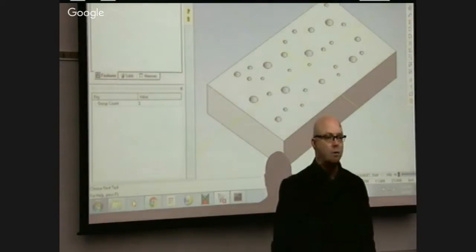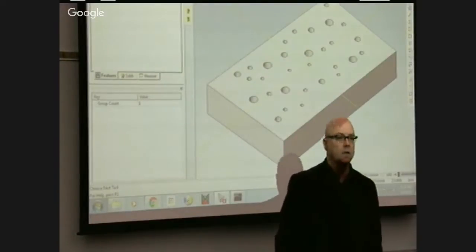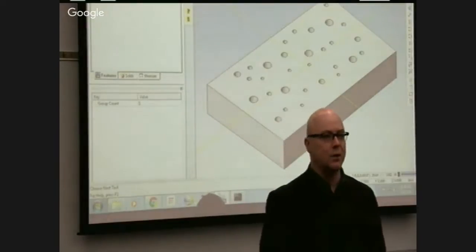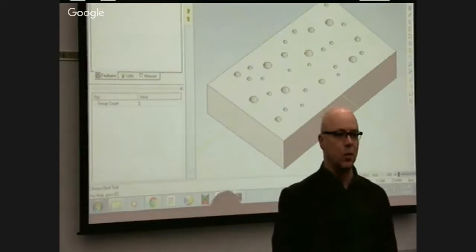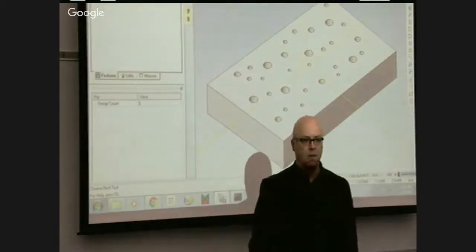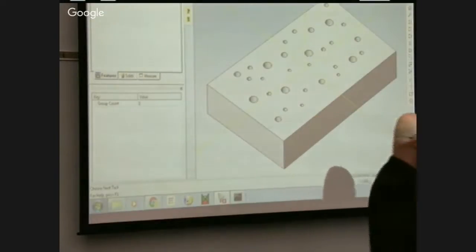You can do all 3 of those methods using the automated interface that you're going to use through the project. You'll have to decide which one you're going to use. Okay? So there's not one that's more right than another. But you'll want to move the origin to the top of the workpiece after the file comes in. And you'll want your program to be adaptable enough that if the file has a different thickness, it would still work. As we go through and do this.